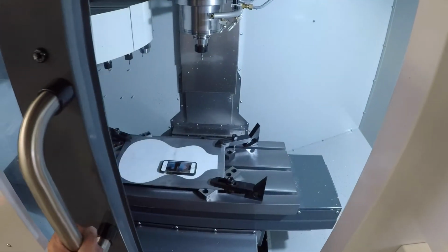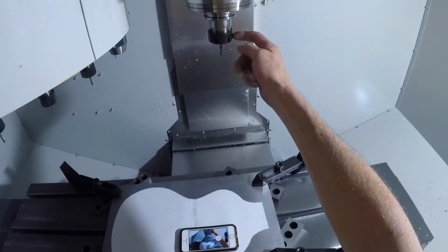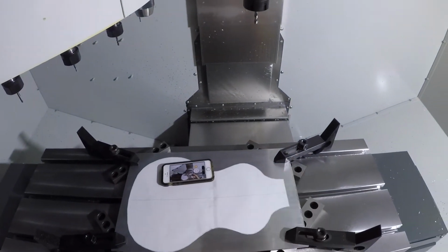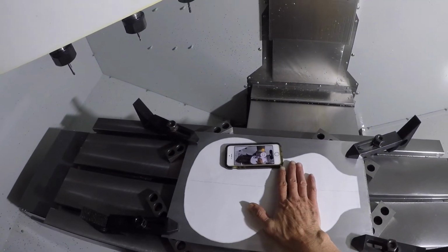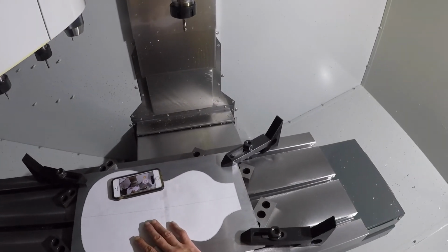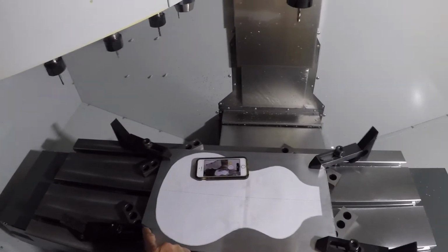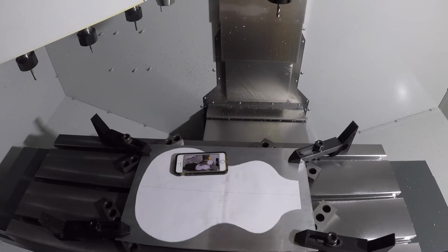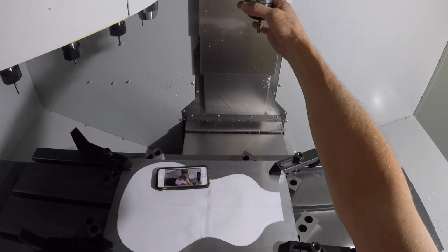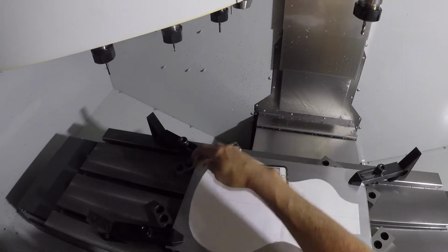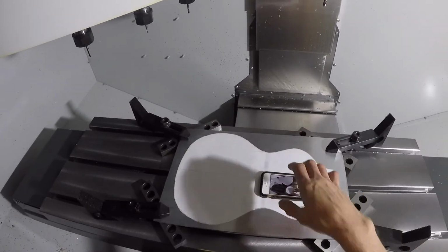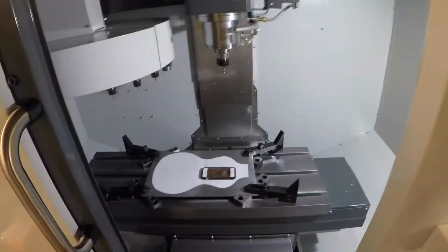Now, this is that 1/4 inch end mill we just put in, and it's going to cut out the pickup pockets, right? But it's also going to cut out my perimeter, and I'm not in danger of the tool hitting anything, but there's a possibility, which I don't think will happen, but I'm going to check it anyway, that the collet could hit one of my clamps. So we could check it. Why don't we do that? Let's just check it, and maybe we won't have to.